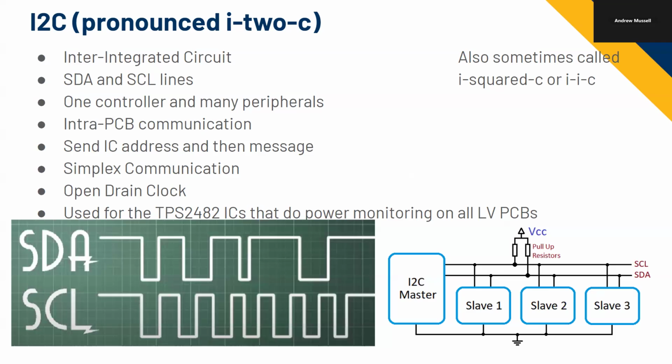So if we turn the clock speed higher, remember what I said earlier about how every piece of copper is like a capacitor on the board. So making this go high and low, you're actually charging that capacitor from VDD and then dumping that power into ground. Because you keep charging it and then discharging it, you're actually using power.